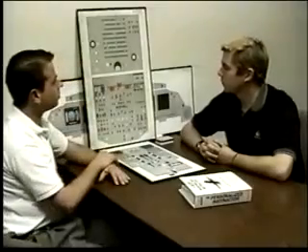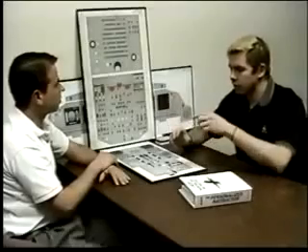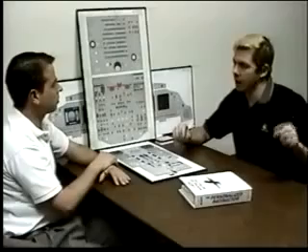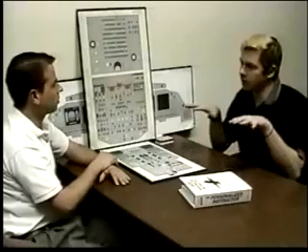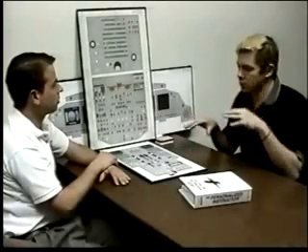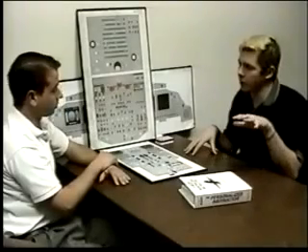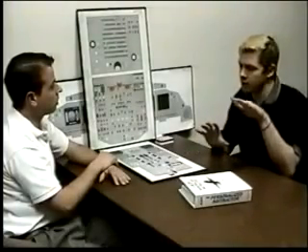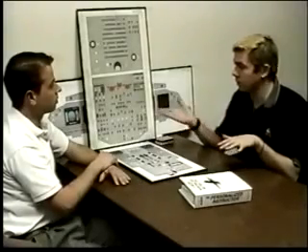Okay. Well, first of all, the IDG oil is cooled from the fuel return lines. So some of the fuel is spun through there, and it cools it off, and then it spills back into the outer wing tanks. When the outer wing tanks are full, it'll spill to the inner wing tanks. Once that senses that it's full, the system will then shut off the respective center tank pump and allow that wing tank to burn down 1,100 pounds. But if the center tank pump doesn't start up again, and it allows the inner wing tank to burn down, it'll then cause this fault to occur.